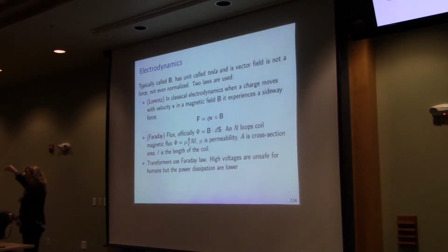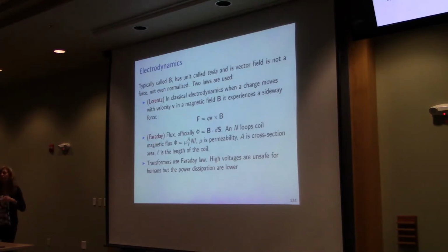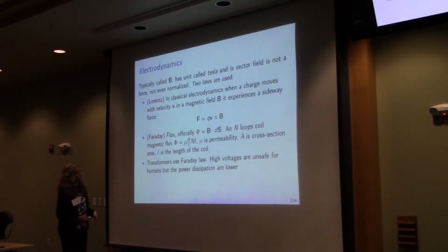And they allow us to go from a higher voltage level to a lower voltage level. And the reason why that's very important is because if you have higher voltage, the thermal loss that you have in transporting power is actually lower. So you want to transmit power at a very far distance at very high voltages, and then you have to scale it down because otherwise people will die. So you don't want to be, in the proximity of a house, at a very high voltage.